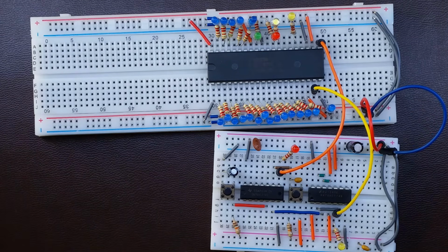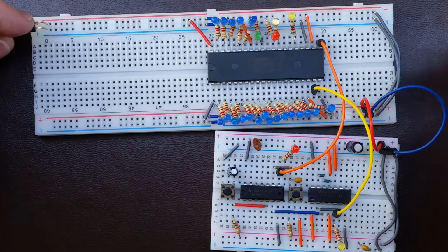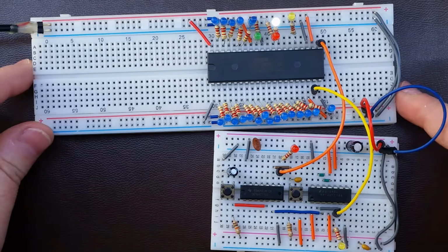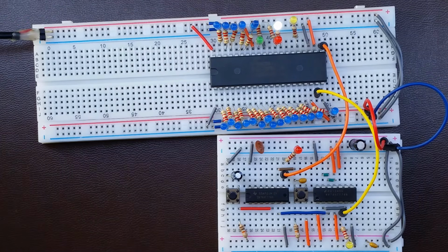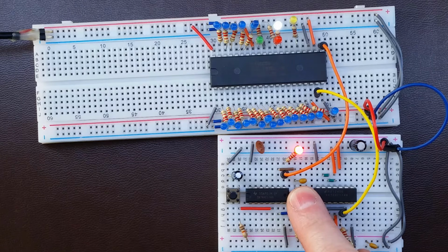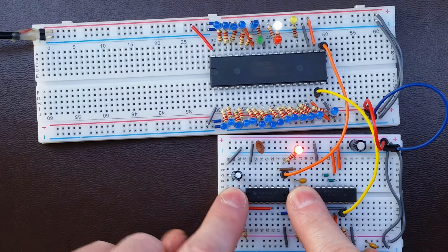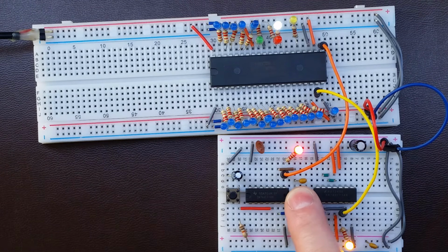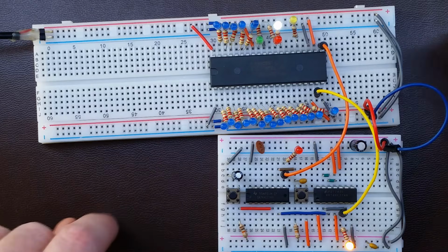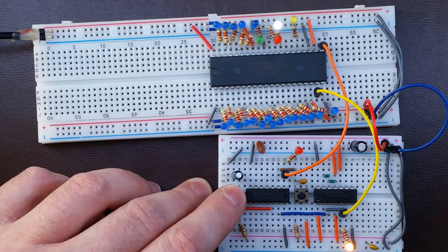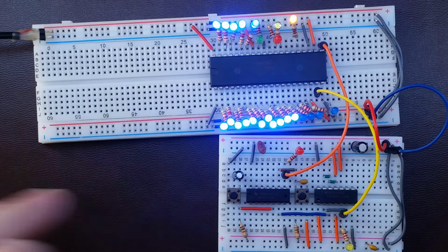Alright, let's start. Let's power it up, like so. Now the state of the CPU is completely random. We first need to reset it, so that's my reset button, which needs, as you remember, to be held for at least 4 clock cycles. So now I can release and wait 7 clock cycles until the CPU starts working. And there we go, something's changed.